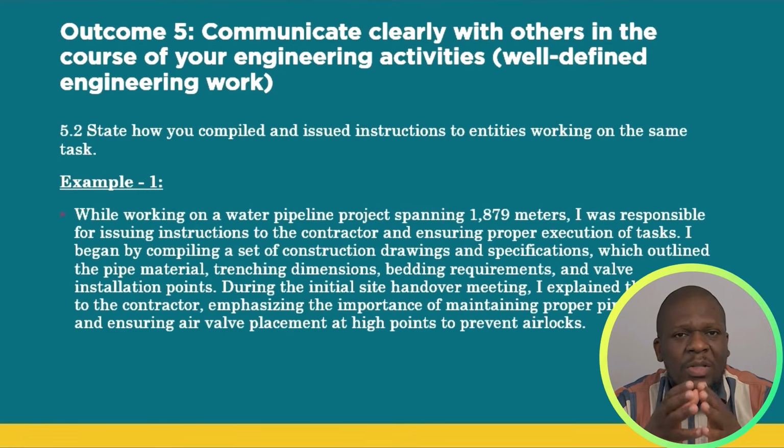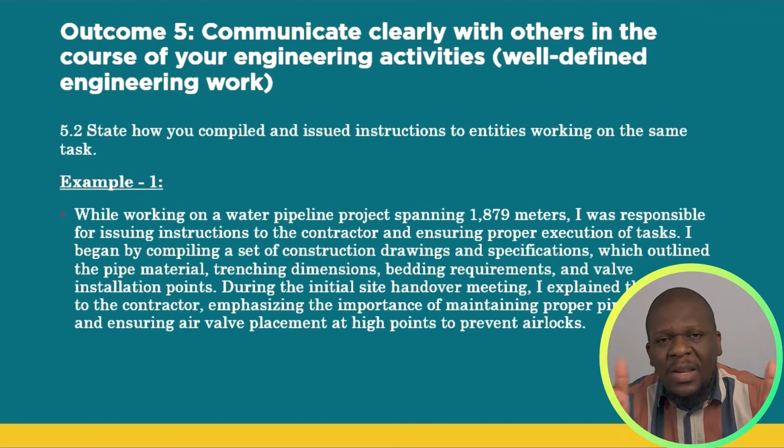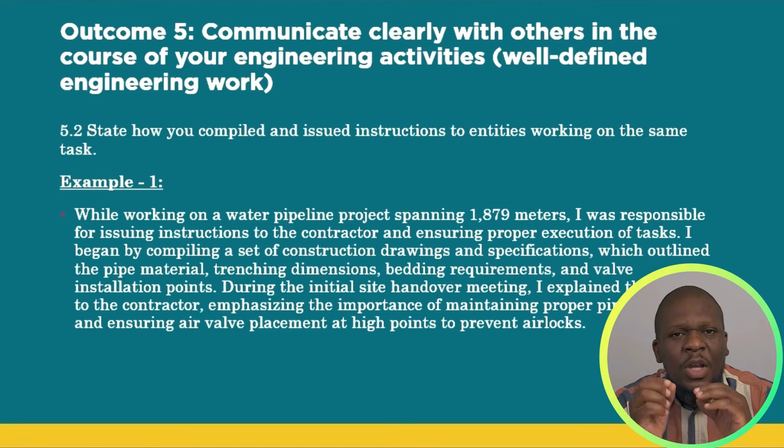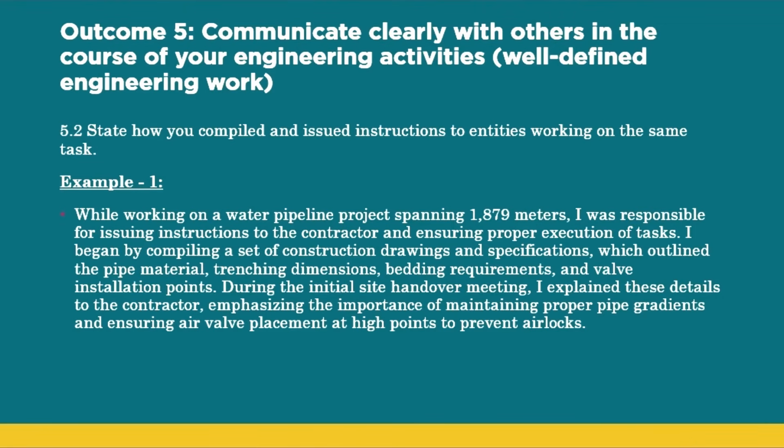While working on the water pipeline project, which is spanning roughly 2 kilometers, I was responsible for issuing instruction to the contractor and ensuring a proper execution of tasks. I began by compiling a set of construction drawings and specifications which outlined the project material, the trench dimensions, the bedding requirement, and the valve installation points. During the initial site handover meeting, I explained all the detail to the contractor.